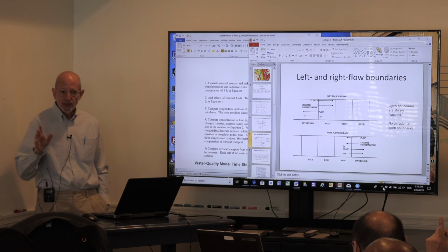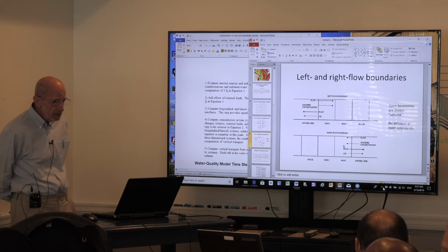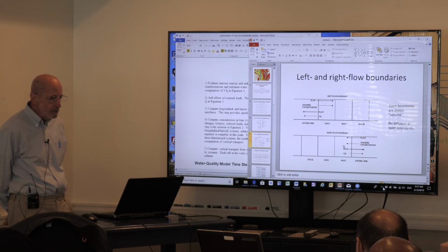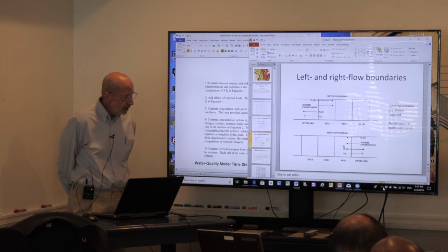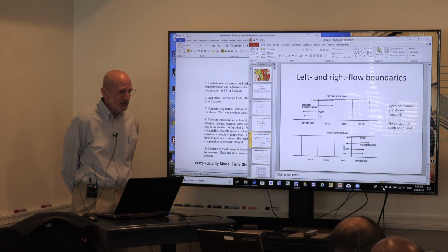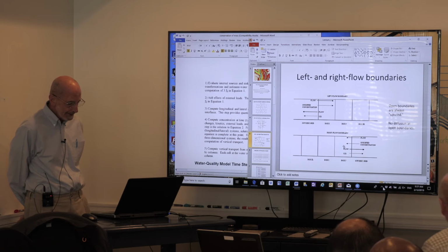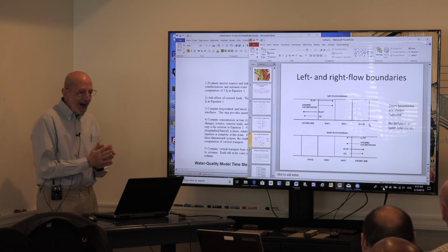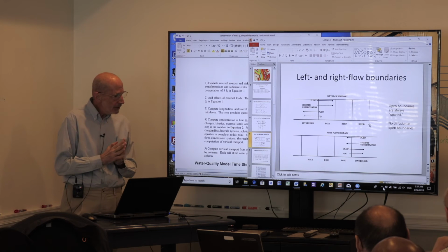Okay, I'll just mention again, so go ahead. Just to understand, an upstream boundary, thinking about it like a dam, or as you said, a river, there's not going to be any dispersion. On your ocean, do you take into account dispersion? We do not. You do not, okay. We do not. And to level with you, I'm not entirely certain what the rationale was anymore, but we do not allow dispersion across boundaries. They're strictly upwind flow. Okay, so actually, look at that, Jim. No diffusion at open boundaries. Yeah, I was thinking of those rivers, but I wasn't sure about the ocean side. Okay.